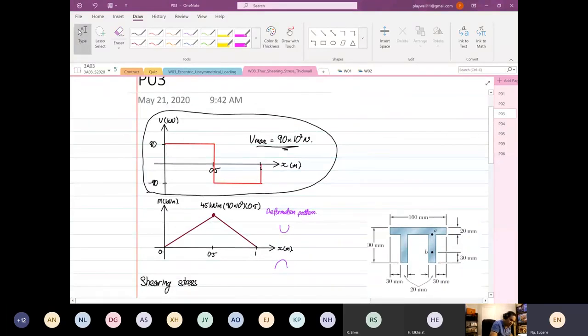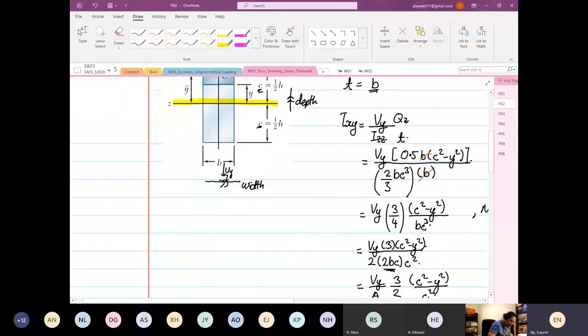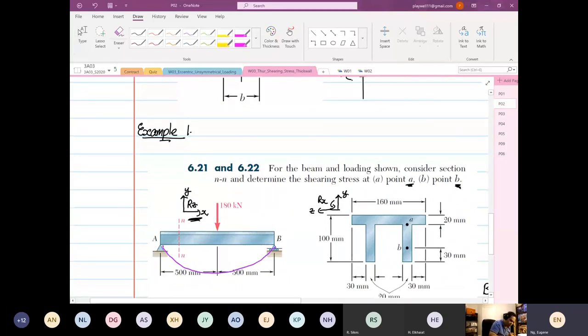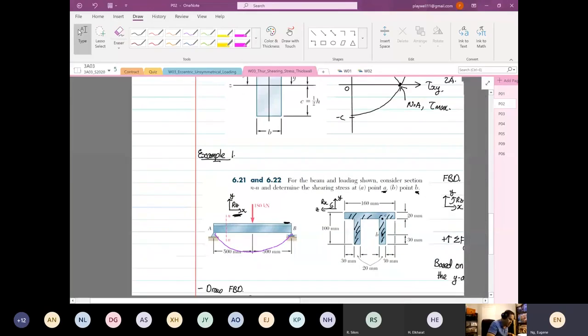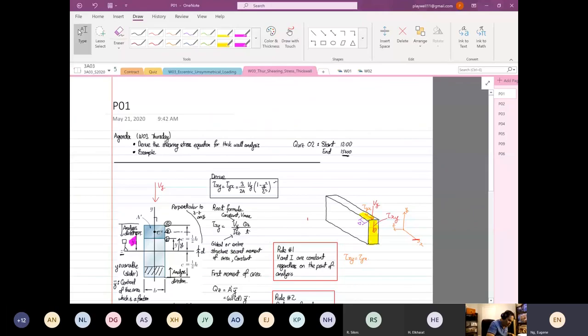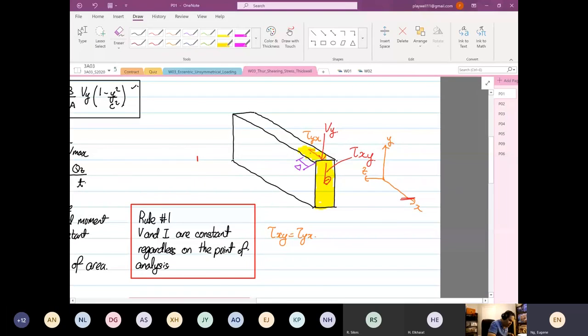Because of the transformation that we have drawn, we're interested in the shear on this entire surface. But this entire surface will then induce a shear at the top surface. Like how I explained earlier, we are finding it on the vertical face, but in fact it will transmit to the horizontal face. We will transmit to this face over here.